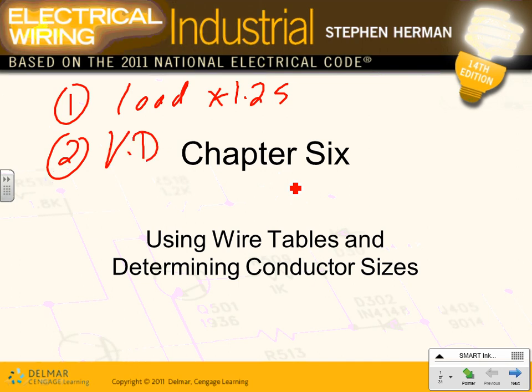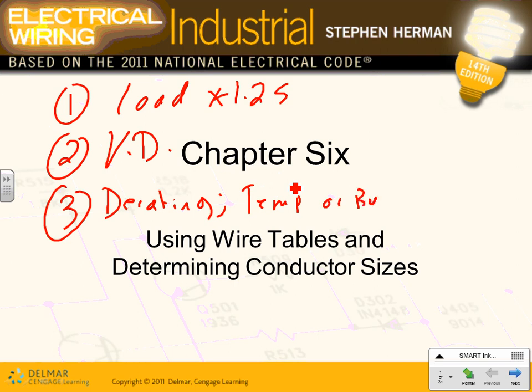Number two, voltage drop. You're going to do a voltage drop calculation for the wire and size based on voltage drop. Number three, you need to do derating. Derating based on temperature or bonding. Bonding, right? And I'm not saying anything that you guys don't know.